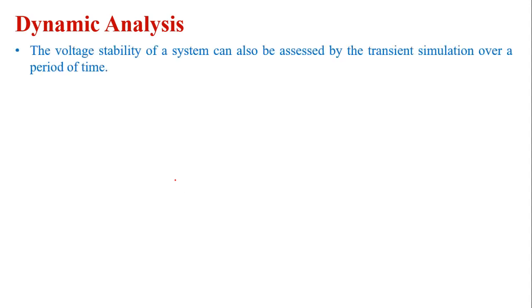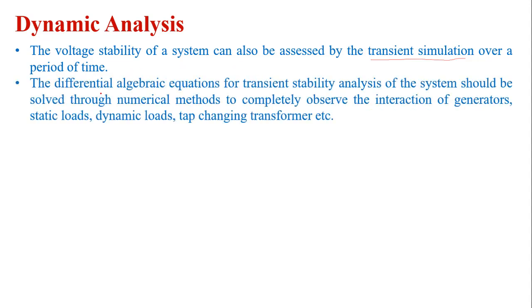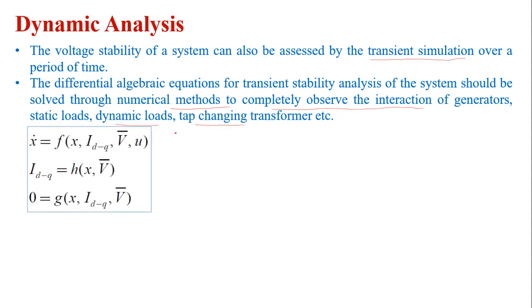So let us then do dynamic analysis. The voltage stability of a system can also be assessed by transient simulation over a period of time. So over a period of time, if we do the transient simulation, we can also find the voltage stability. Here the differential algebraic equations are considered, as for the transient stability analysis, and they should be solved through numerical methods to completely observe the interaction of the generators, static loads, dynamic loads, tap changing transformers, etc. So this is the differential algebraic equation.